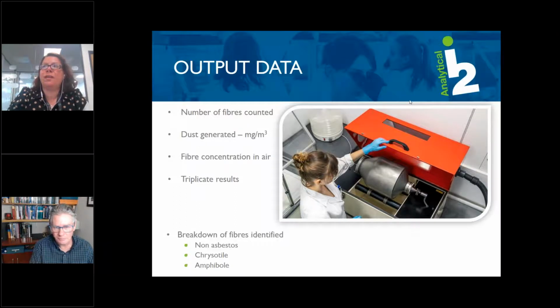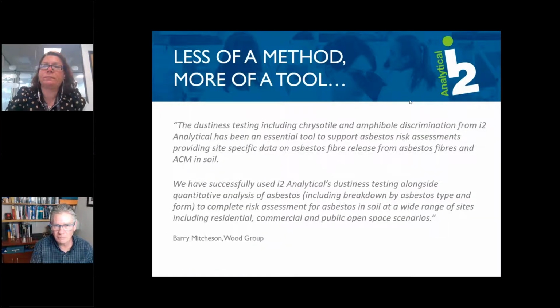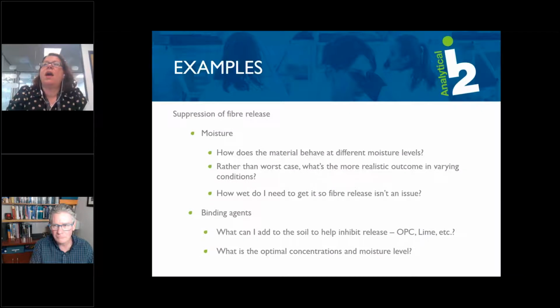But the bit where it's really interesting, and this is just a quote from one of our customers saying they've used it for lots of different reasons, it is more of a tool, it's not a method. We can fiddle with the sample, we can modify moisture, we can add more, we can suppress it, we can look at how much moisture you need to suppress something if you're working on site. If you're looking at remediating a tricky site, we can look at what binding agents can be added into the soil to stop the asbestos being released. So perhaps something that was presenting a problem, perhaps is less of a problem if we can immobilize that material.